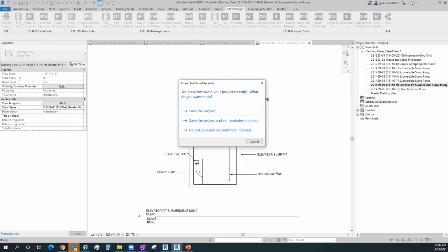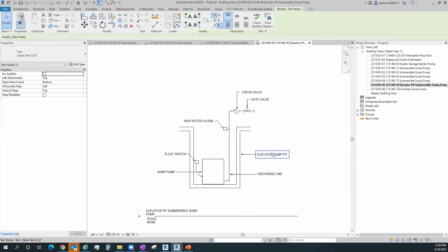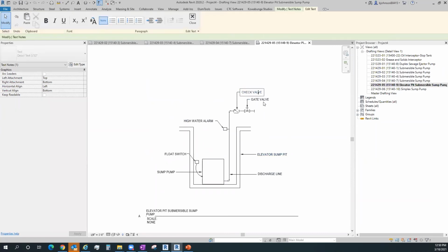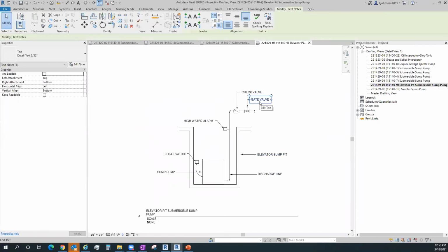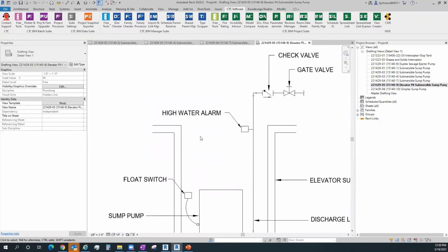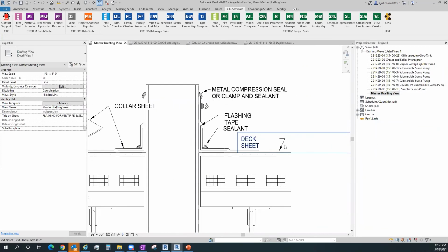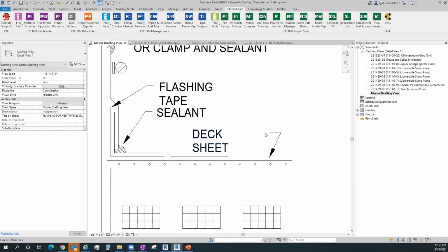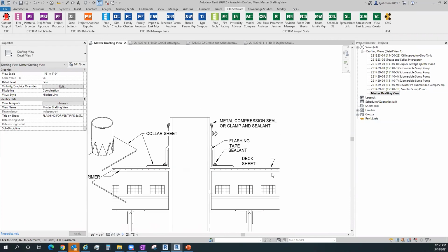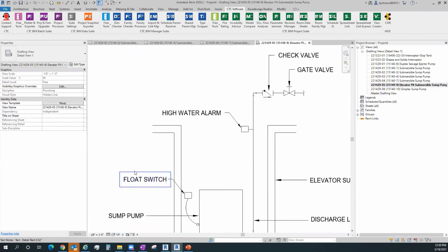For these lower ones down here, I did do the explode text on these, so you can see when I pick on those ones, especially as single lines of text, they don't have the long stretch all the way across to eternity. And the majority of them always align correctly, whereas the one I did first on the main drafting view, that one being an M-text style, it even pushed itself away from my leader at that point. That's some of those reasons why I want to remove some of the problems in my AutoCAD files first, so that they become easier to clean up when I'm back in my main models.